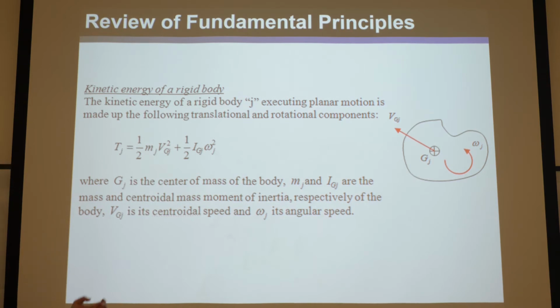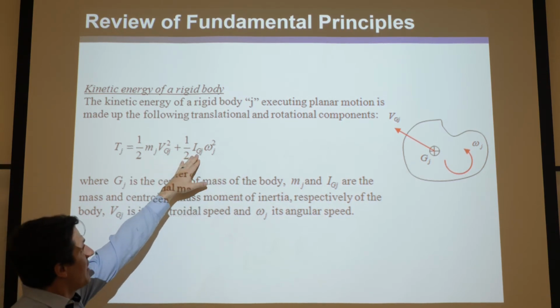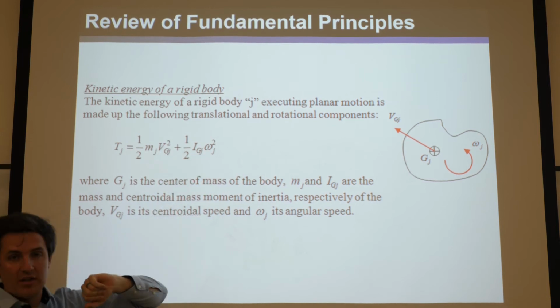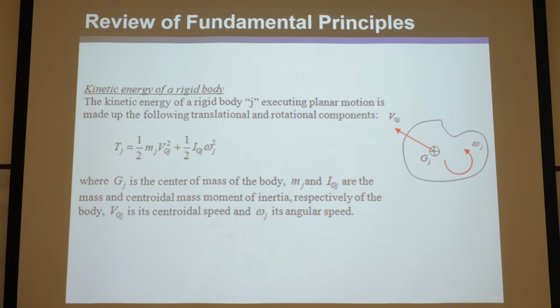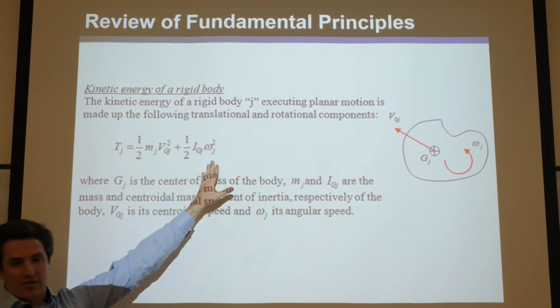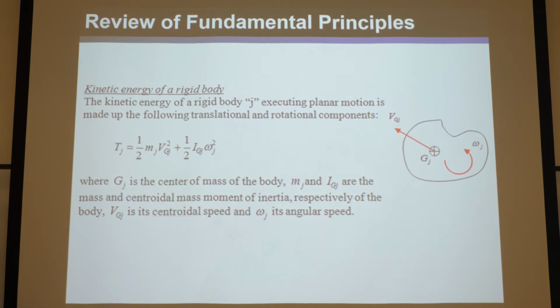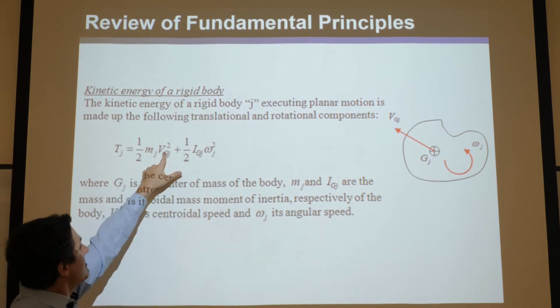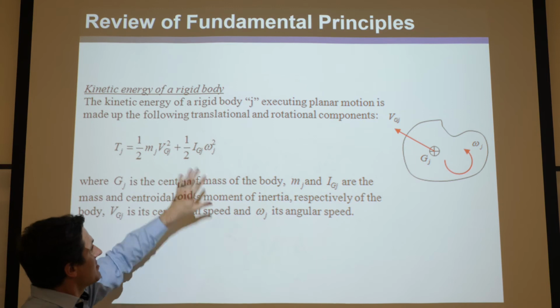So to do that, it's no surprise instead of 1/2 mv squared, it's 1/2 times the mass moment of inertia, which is essentially the integral of r squared dm, if you recall from high school math, where it's basically angular mass, and it depends about what axis it's rotating around, and then of course you multiply it by the angular speed, the magnitude of the angular velocity vector squared. So you can see the analog here. That's like the rotational mass. That's the linear mass. That's the linear velocity, and that's the angular velocity. So it's basically the same thing.